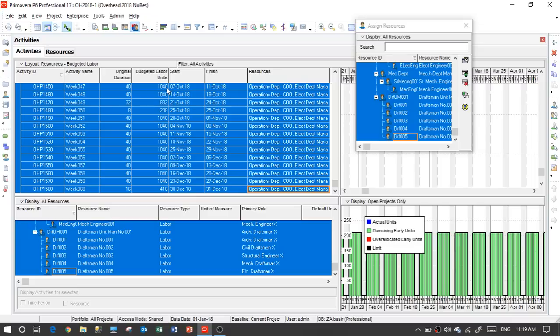One of the issues is that big people in big positions can't book 1 hour as a total for one project because it will be very big. So what we do is play with the price unit by dividing it into units, so it will take less than 1 hour, because Primavera gives us a 1 hour estimate only for cost. It can't give us less than 1 hour.